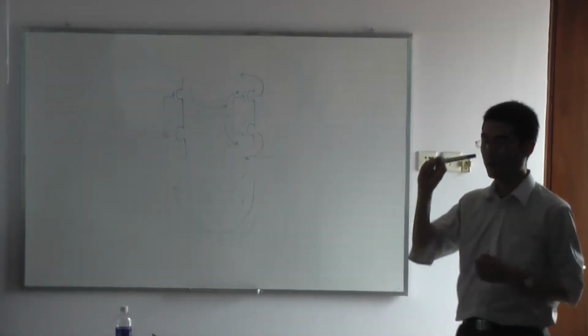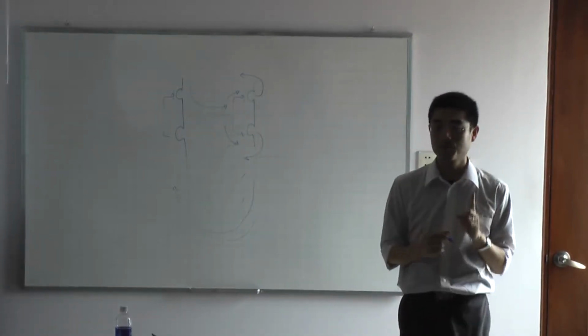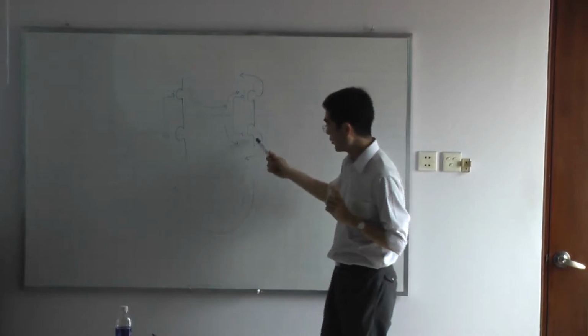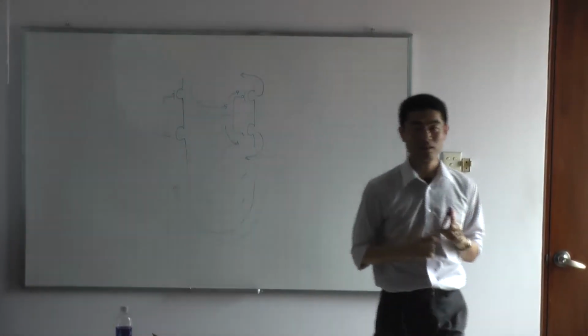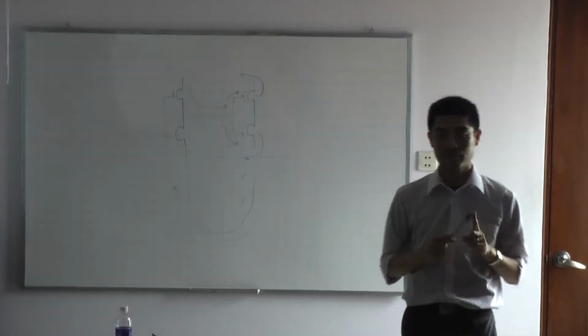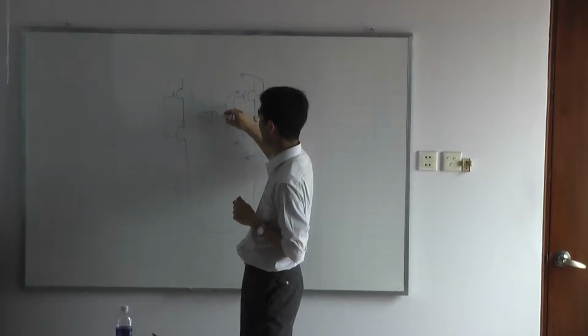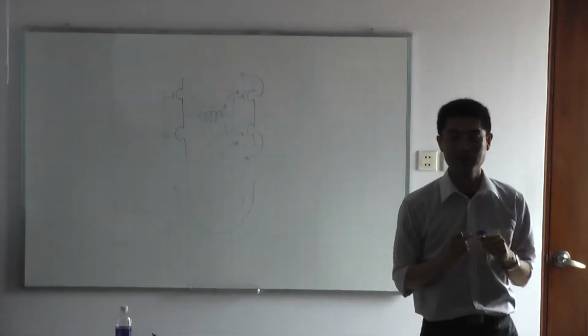And the inductance value is proportional to the loop area. So once you have this kind of large loop, you will see large inductance. In this case, you will see inductance here, and it will degrade the performance.